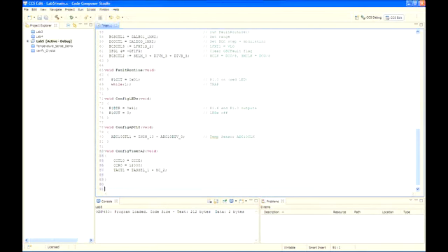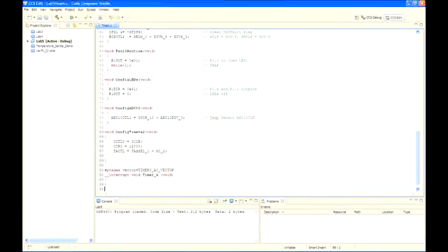These lines of code identify this as the timer ISR code and allow the compiler to insert the address at the start of this code, that's Timer A, into the interrupt vector table at the correct location. That's TIMER0_A0_VECTOR. So the purpose of these two pieces of code is to take the address of Timer A and plug it into the correct place in the vector table. Look it up in the C compiler user's guide. This user's guide was downloaded in Lab 1.